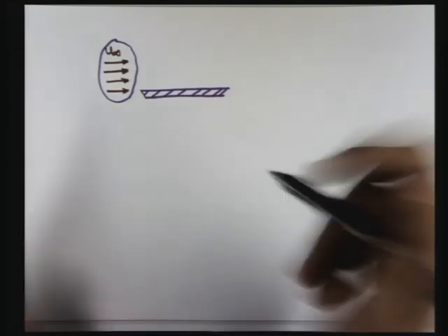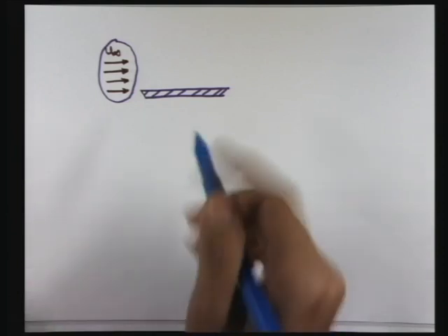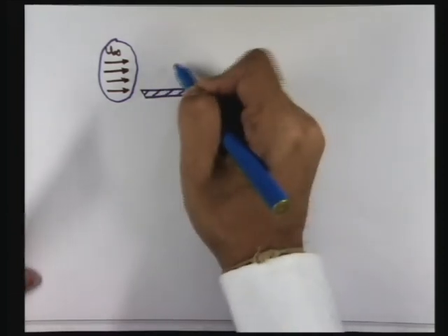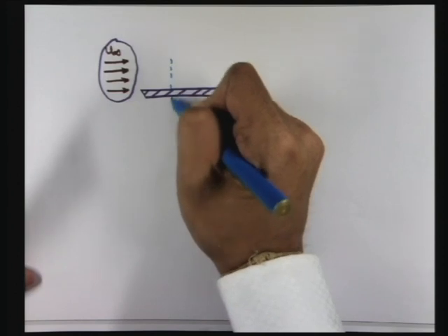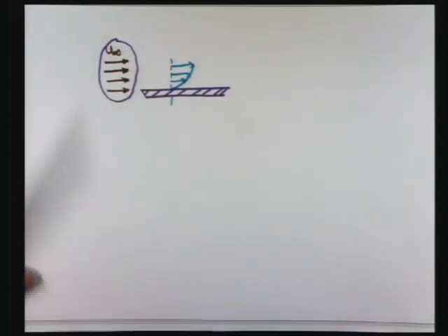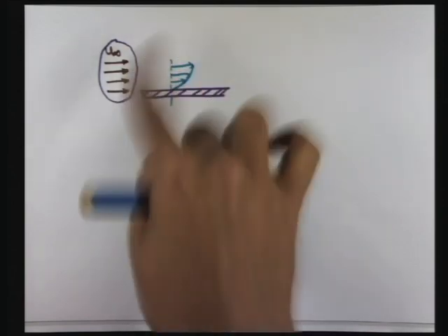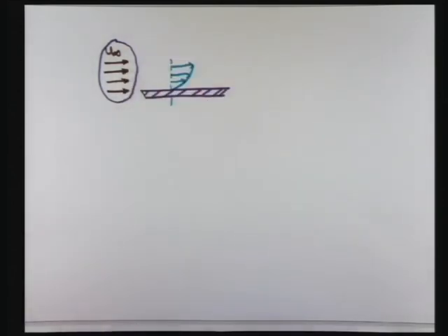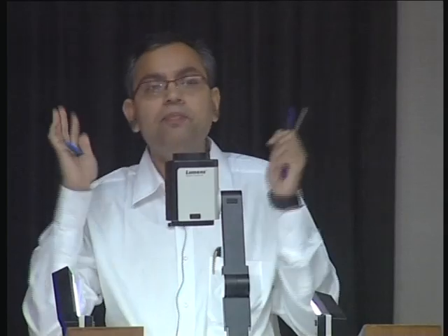Now what we have discussed on the first day of this workshop is that because of the effect of the wall there is a velocity gradient that is created. There is a gradient of velocity along the cross stream direction that makes this flow rotational. So there was an initially irrotational flow, but the effect of the wall, or the viscous effect, has made it rotational. How to understand it physically? I am giving you a very simple example.